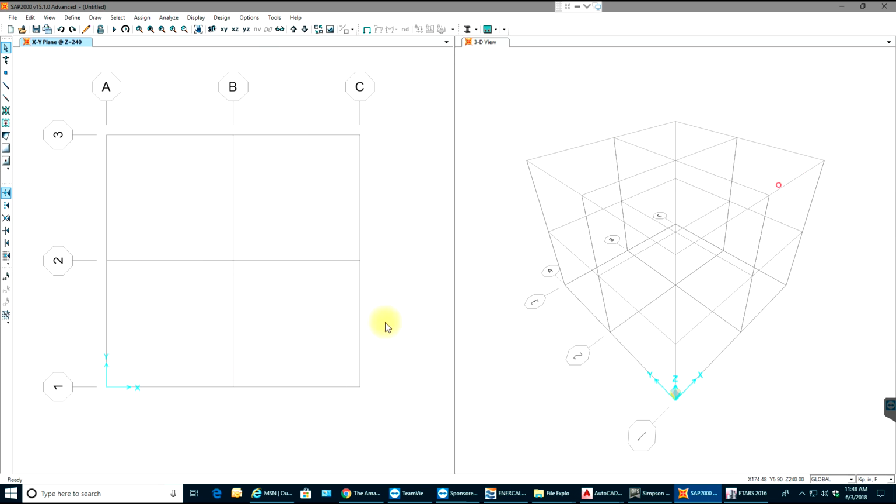Now coming to your grid. Now you can see this is the XY plane at 240 inches. Let me just change this to feet. So now it's at 20 feet, and let me go to 10 feet below it. I need to select move down in list, so that it will select the bottom grid, which is at 10 feet.